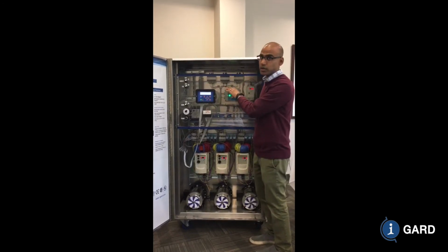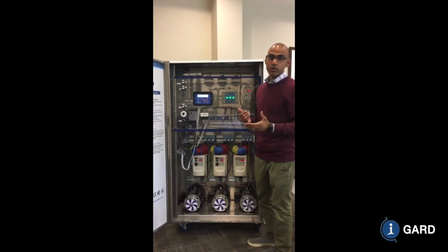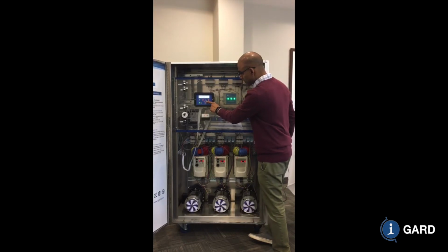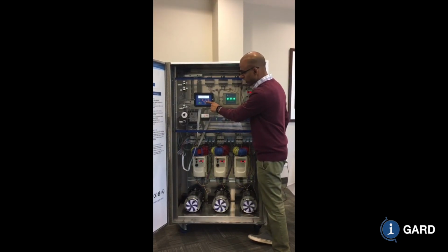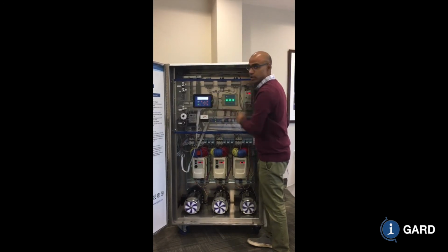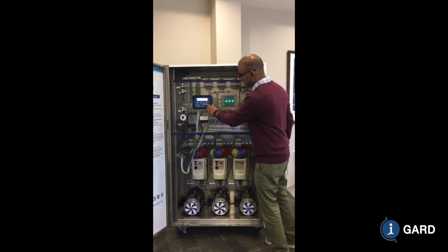From the feeder page, if you hit the right button over, this is the pulsing page where you can initiate pulsing. You would initiate pulsing on the occurrence of a fault as a method for fault location. And the next page is the DRM page. We don't have a DRM on this lineup. And the page after that is the arc detection module page.